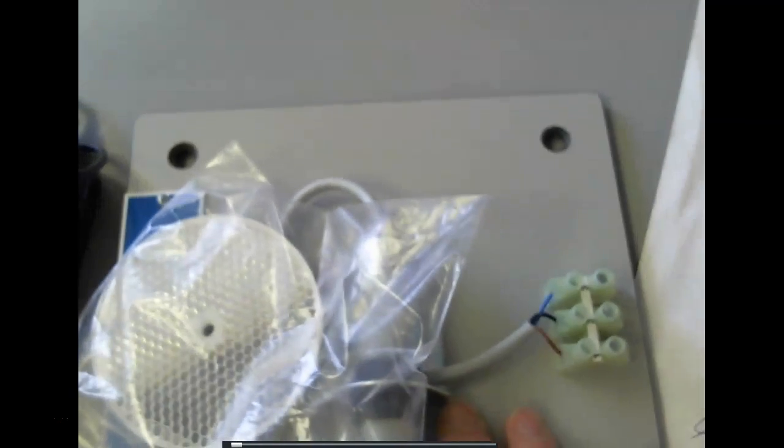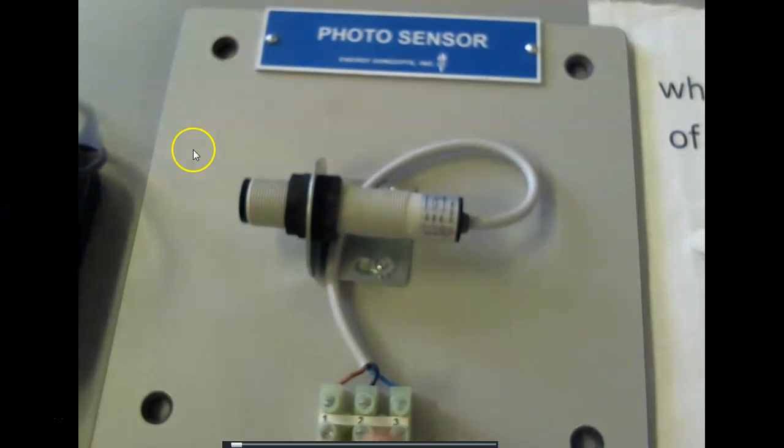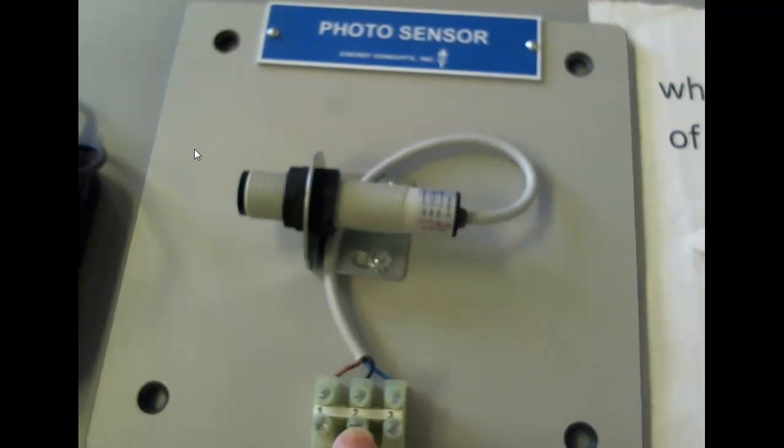So this is the 3-wire sensor. So here we are going to connect. What's the connection? So I got a brown, black, and blue. So brown will go toward L1, blue will go to L2, right? You understand that? And then the black will go to the load. Are you okay there? Okay.